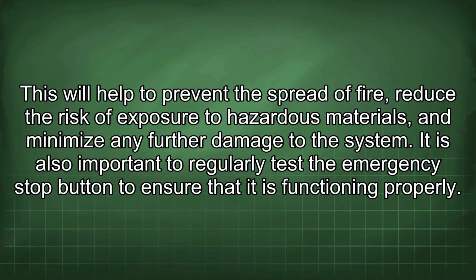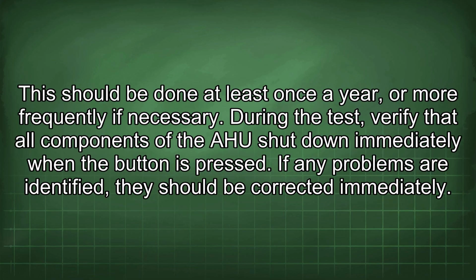It is also important to regularly test the emergency stop button to ensure that it is functioning properly. This should be done at least once a year or more frequently if necessary. During the test, verify that all components of the AHU shut down immediately when the button is pressed. If any problems are identified, they should be corrected immediately.